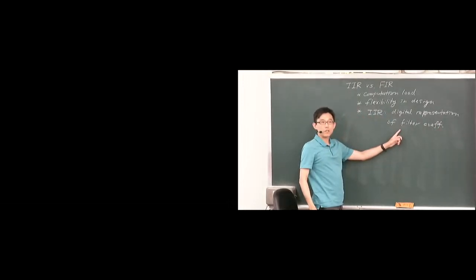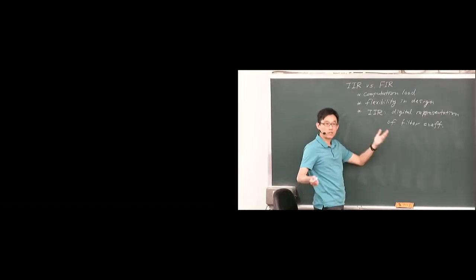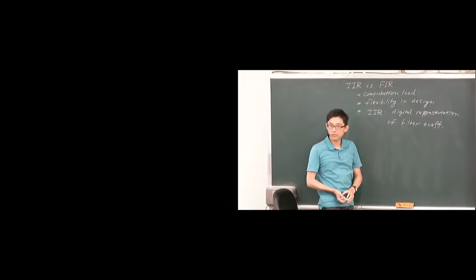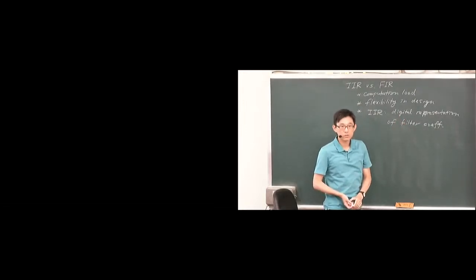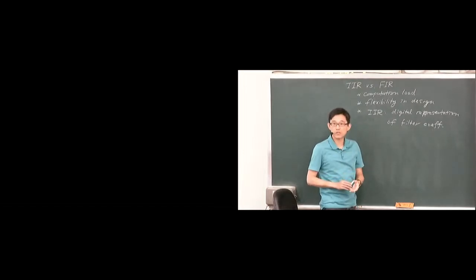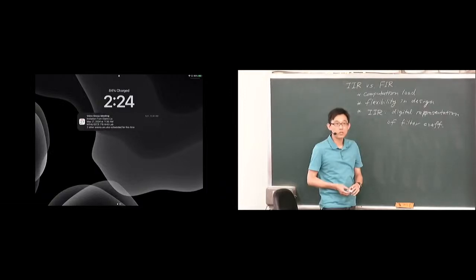So far we have discussed a bit about quantization. In what context? Does anybody remember? Quantization introduces quantization noise, right? And sometimes it sounds like white noise. In a previous homework, we talked about digitally representing all the samples using zeros and ones. But we also need to represent filter coefficients with ones and zeros. In concept, they are real numbers, but we always have a finite resolution for any number we use in any computation.